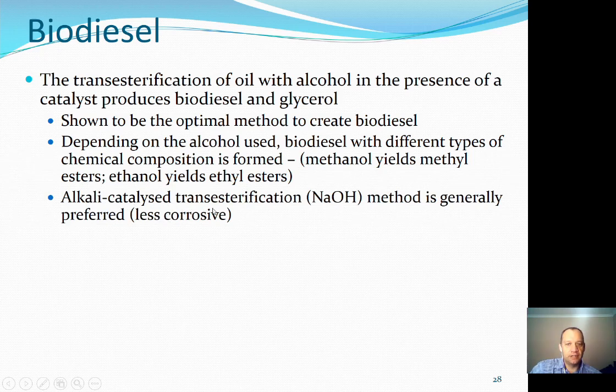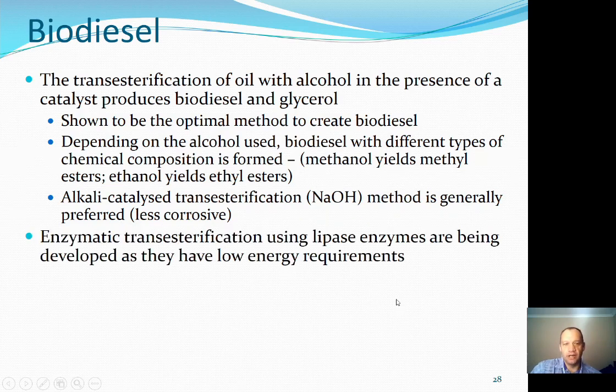Alkali catalyzed transesterification is generally preferred as it is less corrosive, and people use sodium hydroxide or potassium hydroxide for this purpose. Although in some cases an acid catalyst is preferred if there's a higher water level in your oil. Enzymatic transesterification is also an option.